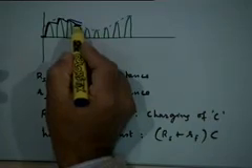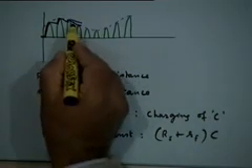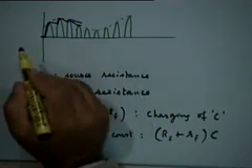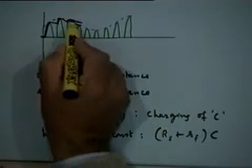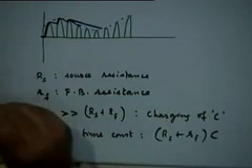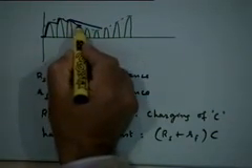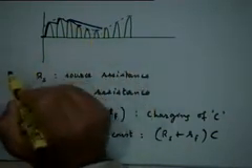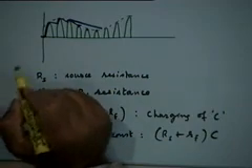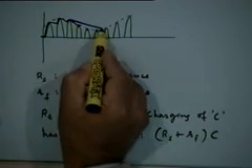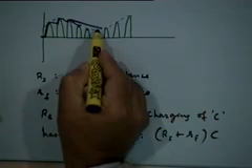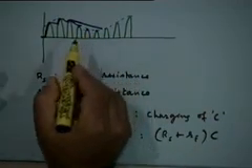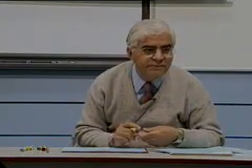Is that good or is that bad? It is bad because you are not following the envelope, right? So this would lead to a kind of clipping. You would miss all these variations in between, right? So while this discharge time constant should be slow, it should not be so slow that it does not follow the fast fluctuations that might take place in the envelope itself, right?